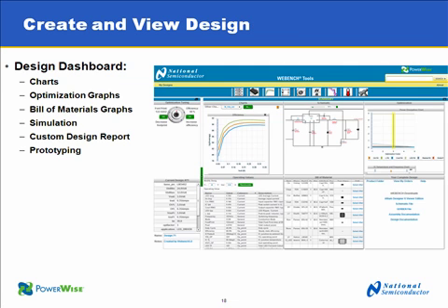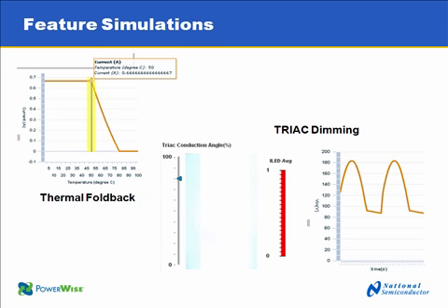After that, you create your design after you've selected your driver, and you can view it. This gives you the opportunity to look at the operating values charts, graphs, and bills of materials. You can simulate, you can have a custom design report, and for devices that have it, you can do the Build It prototyping step.